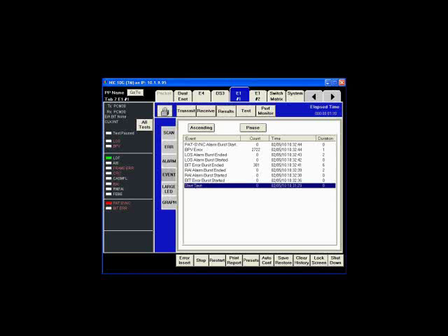Okay, so the test started here at a certain time, 10:31:29, and then we had some bit errors, and then we had this alarm, and this bit errors ended, then we had the bipolar violation errors. So it just gives a list of everything that has happened during the current test. And you have this little button that says ascending or descending, so you can have the start test at the top, any of that. And if we stop the test, hopefully it'll tell me, yeah, end test. So then this can be printed, and it's very useful information to the customers. Nice feature.